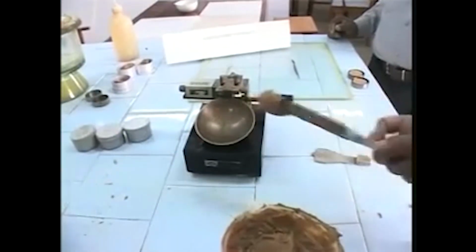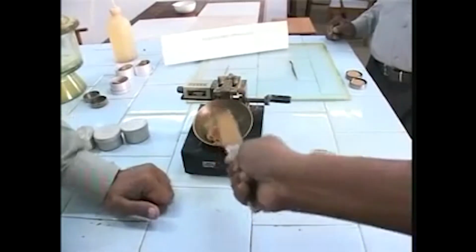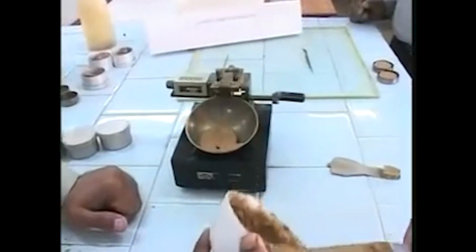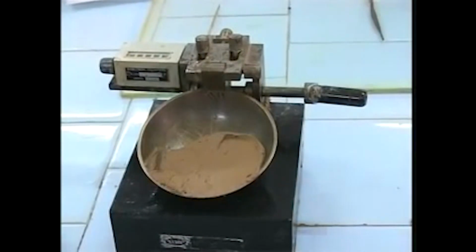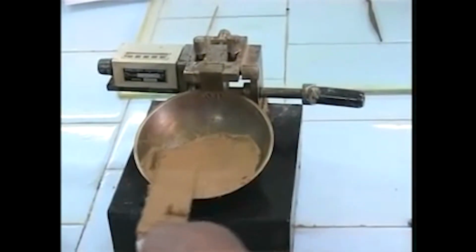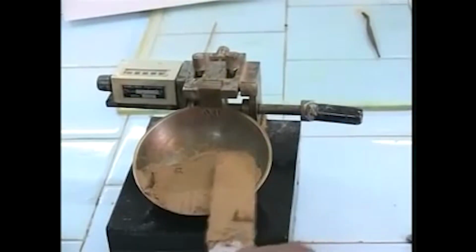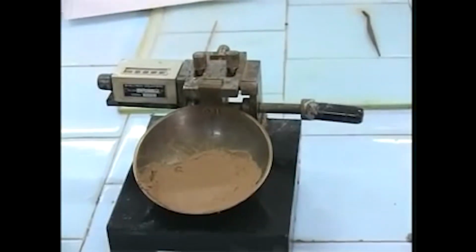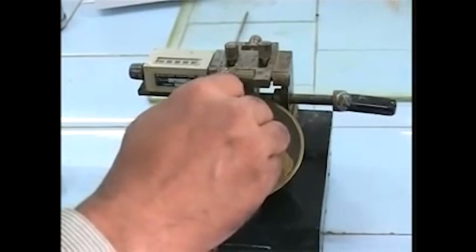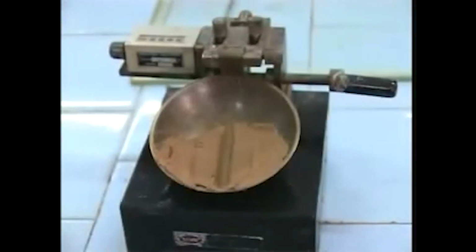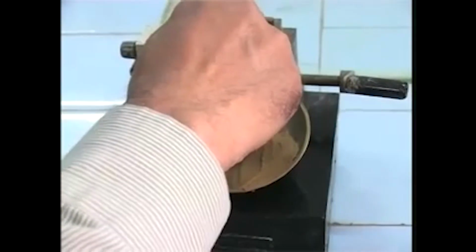Okay, so now we are starting. So you see now we are preparing the pat in the pan, making sure that there is no air entrapment within the volume of soil, and the surface of this particular pat should be approximately horizontal, and then we use the grooving tool as you see here to cut a groove at the center of the clay pat, or pat of fine grained soil, and this is the groove that we have constructed here